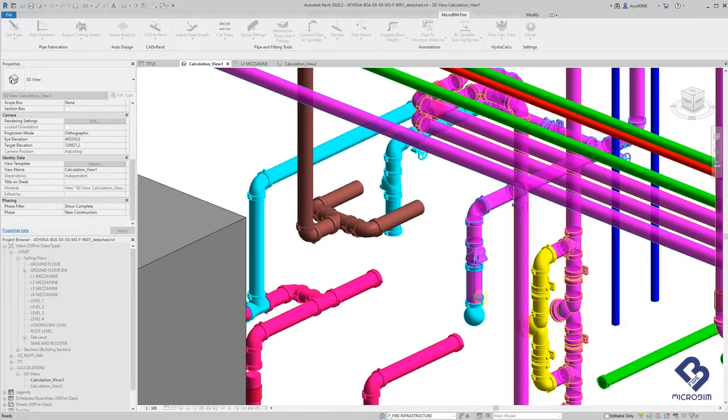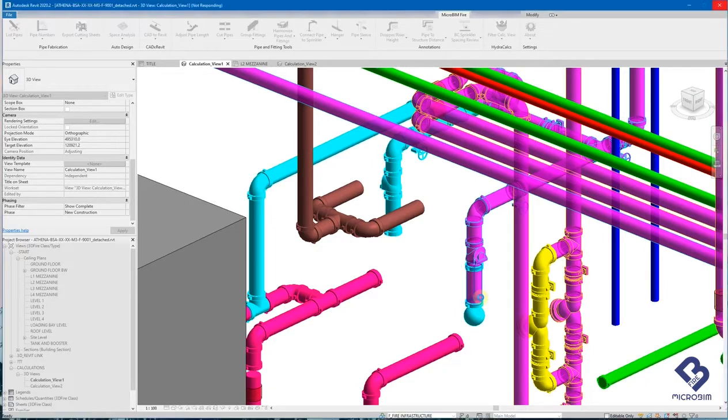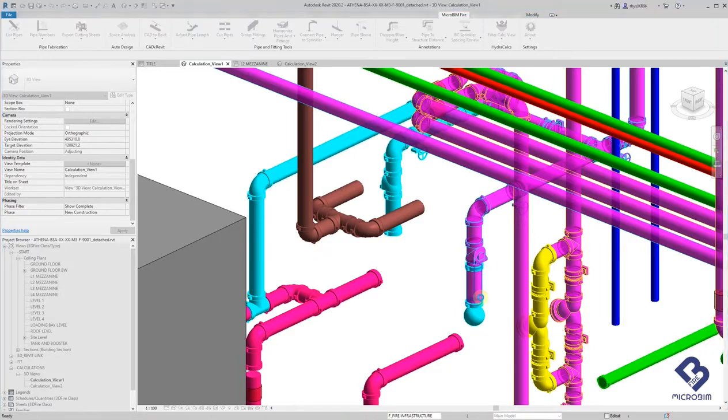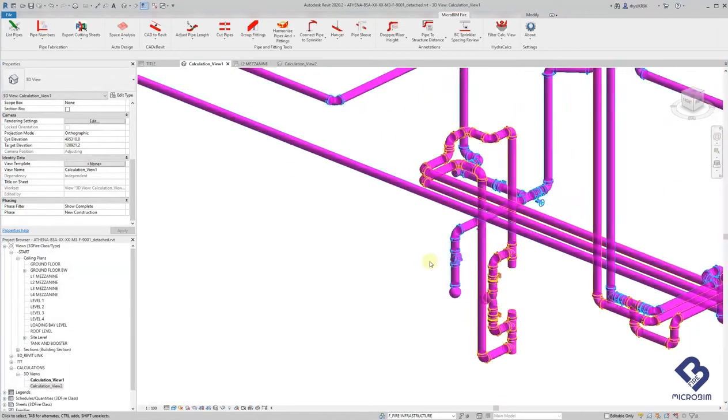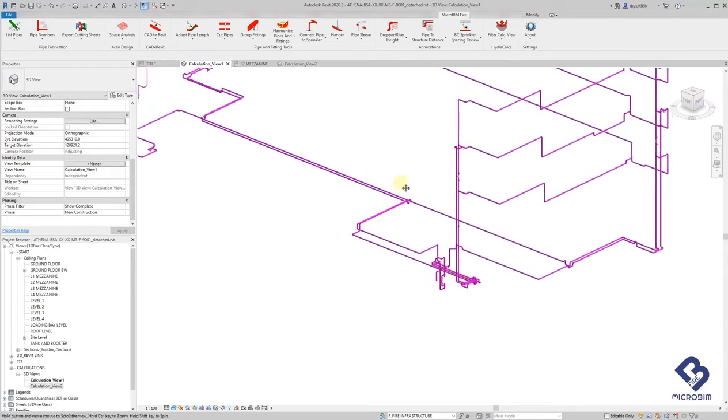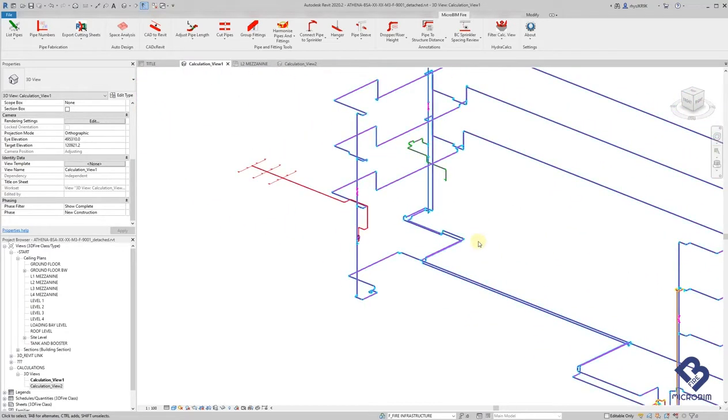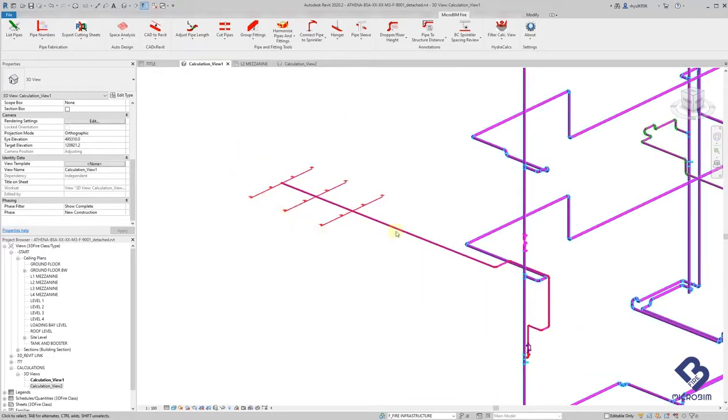This will then filter out all the unnecessary elements, pipe, and sprinklers and hydrants that are not required for the area that we've nominated in order to calc. And we can see here that the filter has eliminated all of this unnecessary information. It's kept our hydrants, and there are our 12 sprinklers for operation.